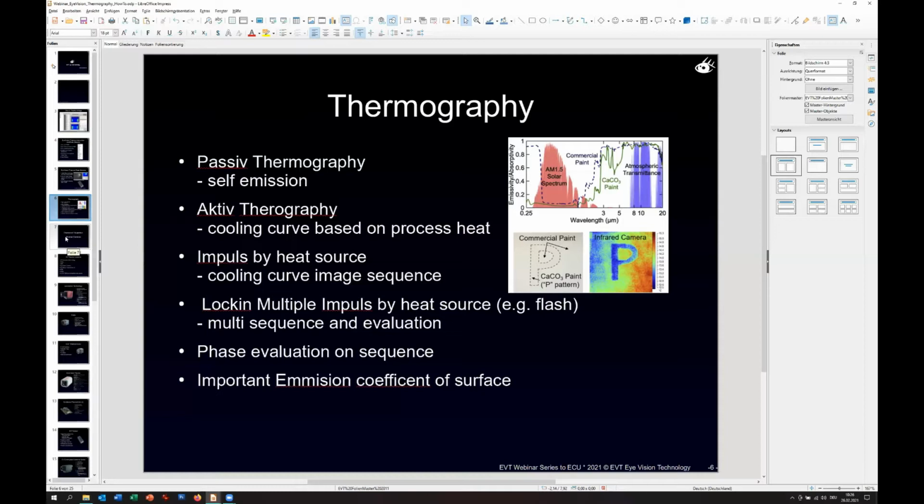These are reflections, and maybe you're looking for a very low heat source, but in reality you have behind your part maybe a lamp, and the reflection of the lamp heat source would result in what you see, and not what the camera sees. You don't see it, and that's a major problem in most solutions of thermal imaging.